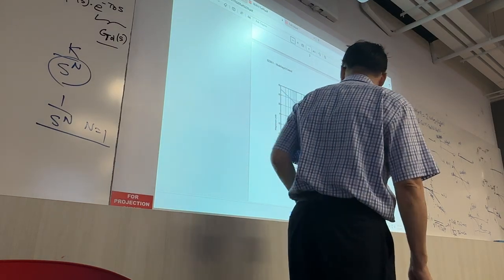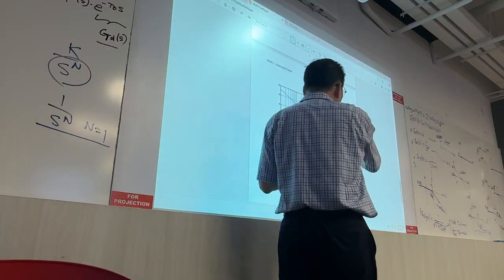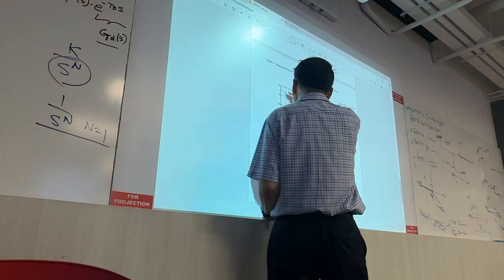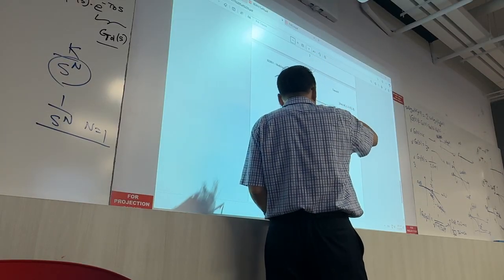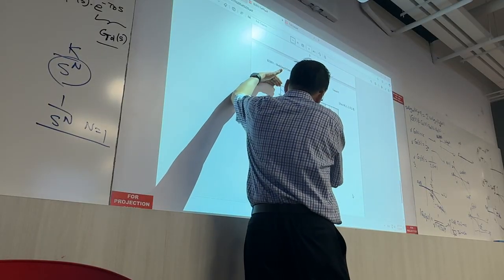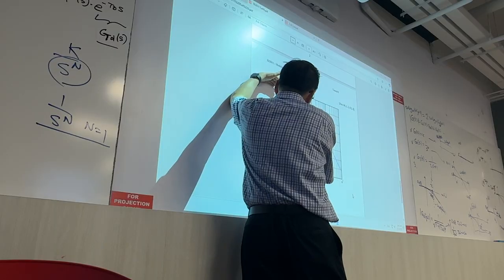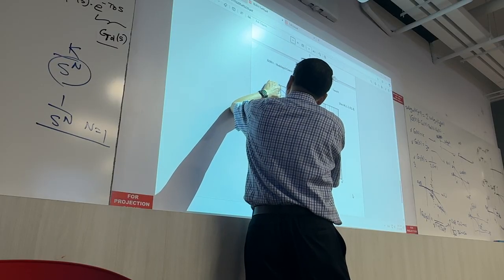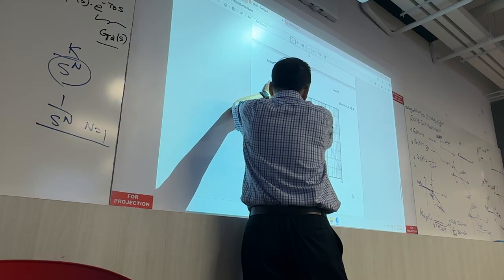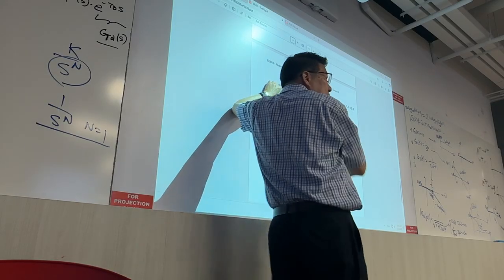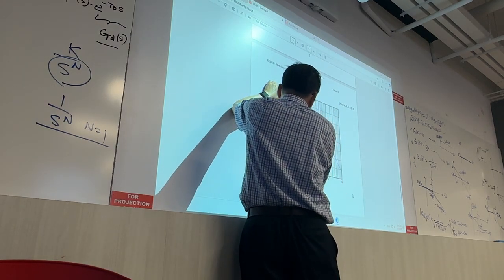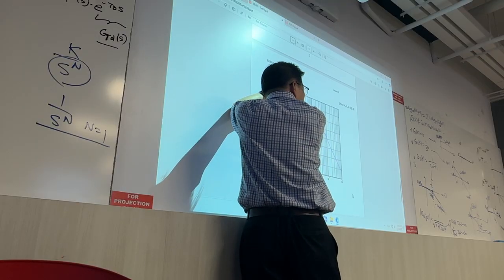Now, as I said, given this, you want to fit in the lines, the asymptote with a fixed slope: 0, minus 20 dB per decade, minus 40, minus 60, and so forth. So the first thing you want to look at is the left portion. In 1 decade, you see how much change. This is around 50, this around 30. So you can see that this is minus 20 dB per decade. So you draw a line, minus 20 dB per decade, and fit in.